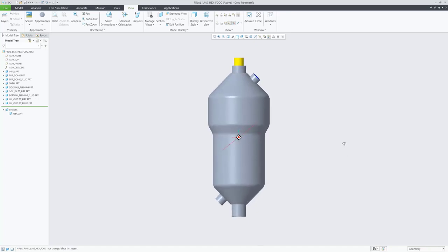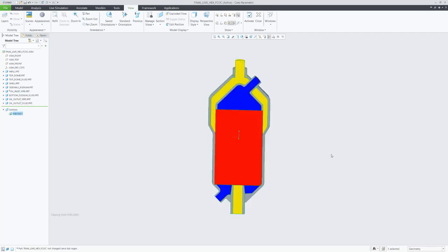Creo is my preferred design tool. You can see here that I've changed the bottom port and bottom section to be at about 45-degree angles to make them self-supporting during the print process. Looking at a cross section, we'll see the other parts and modifications that I did.